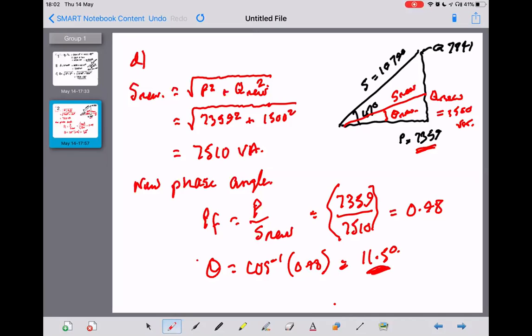Well, there's a chance that when you go to this power factor here, cos theta 0.98, that you round it, and then you're rounding it again down here with the angle. But it hasn't made any difference. The thing I would like to check as well is I always like to see what the power factor is, because I did write one and I got over 1, and I didn't notice until I got to the end.